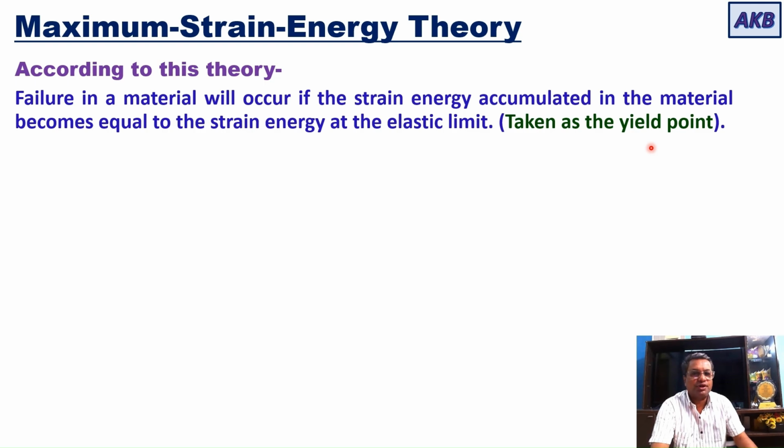Yield point is a point beyond which the material begins to plastically deform. Below the yield point, the material will be elastically deformed. That means it will regain its shape and size after the removal of applied load.